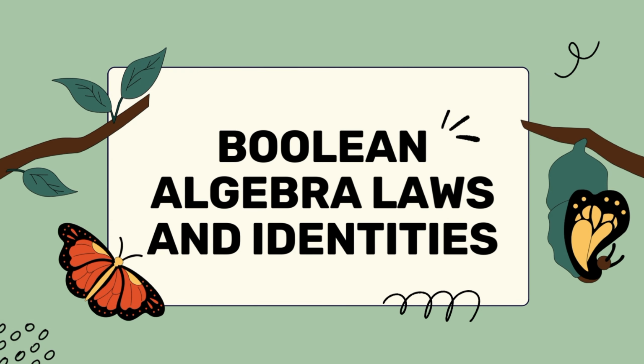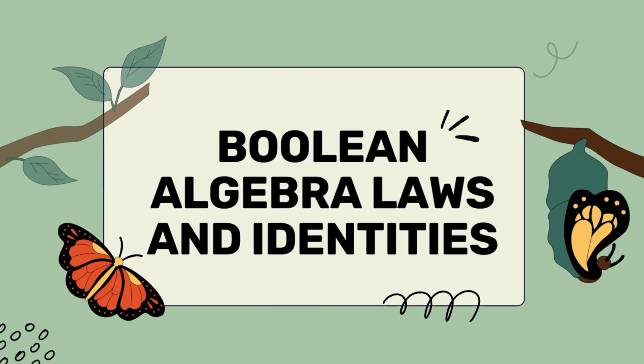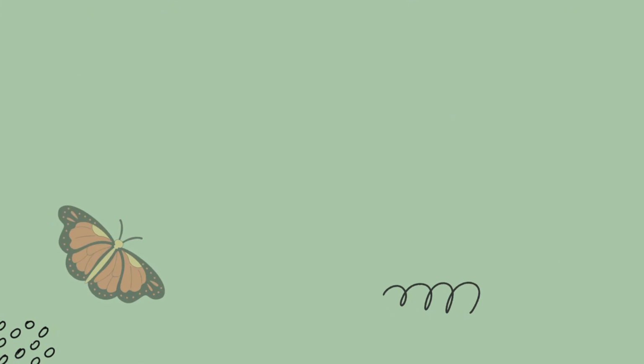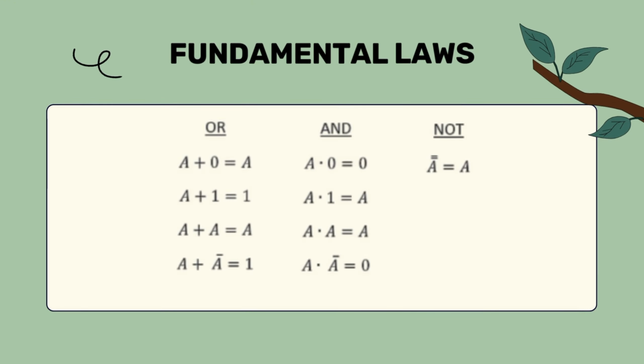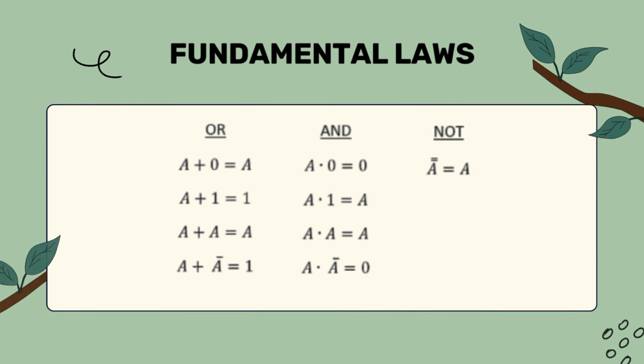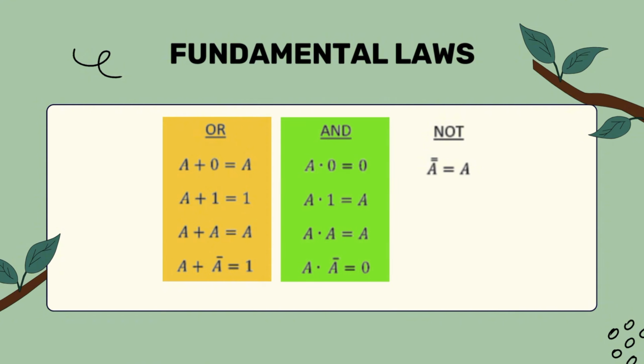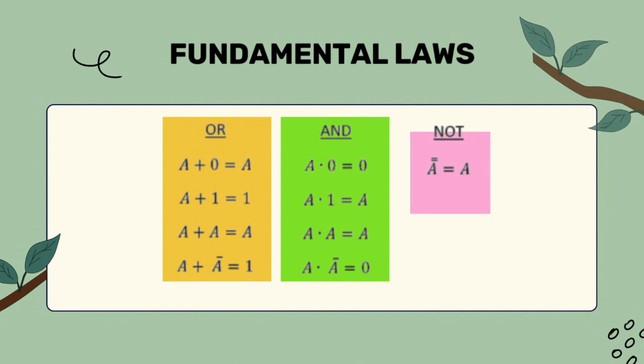When formulating a mathematical expression for logic circuits, it is important to have knowledge of Boolean algebra, which defines the rules for expressing and simplifying binary logic statements. Fundamental laws: OR becomes the sum of variable inputs to obtain a result output, AND becomes the multiplication of the factor inputs to obtain a product output, and NOT is the inverse of the input.